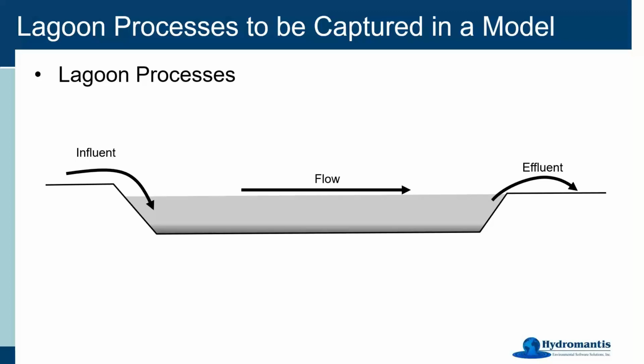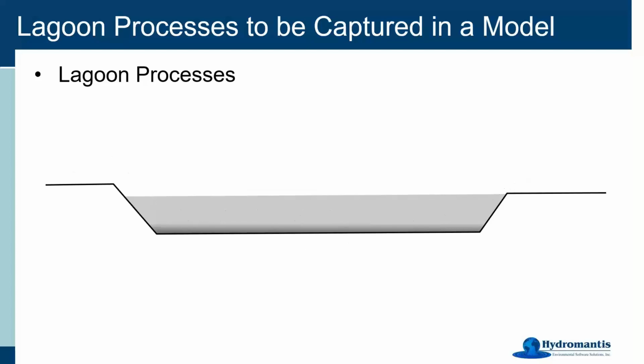But another important factor that can come into play with a lot of lagoons is backmixing. In a lot of places, there's a resuspension of the solids potentially, or at least carrying the solids back as they move around in the system. It is often a very difficult thing to quantify with a measurement, but the modeling will indicate that there is some backmixing going on, because we are seeing the biomass present in some of those earlier upstream systems. So generally, one of the approaches we find we have to take is that you have downward flow, but with some backmixing.